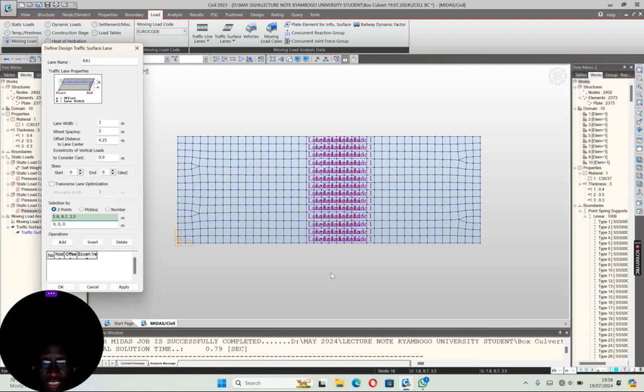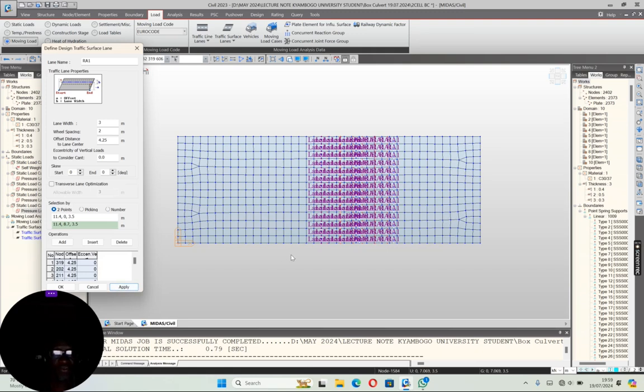Please don't change the center. The center remains. This point, you don't change it. It has to be the same you are using for applying. There you go. So now you applied both the lane and the remaining lane on the right hand side as positive. That means the left hand side will be the negative value. The same thing but negative, and with the same data.